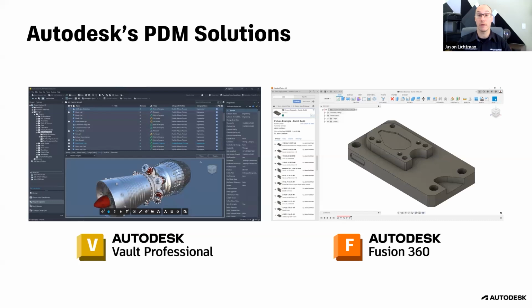The key, though, is that for a certain file, like the one I showed earlier, there's really just one file, and the system in the background is keeping track of the older versions. But you're only looking at and working with one file that represents the object, whatever version it happens to be, right? And again, Fusion 360 is going to be the tool that you use for designing, analyzing, and manufacturing. And along the way, it's doing all of that stuff for you. So it's keeping track of your data and your versions. You could always go back and get older versions. But the key here really is that you don't have this organized chaos like I showed you earlier from Windows Explorer. So that covers PDM.